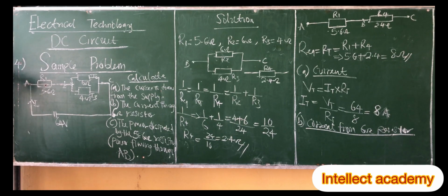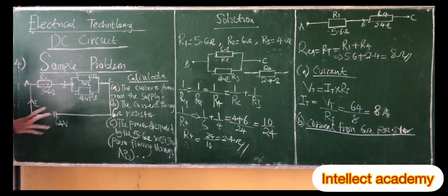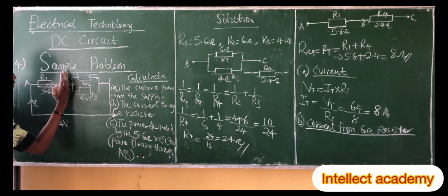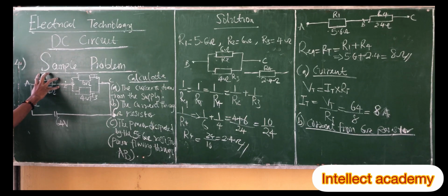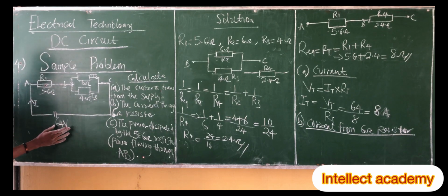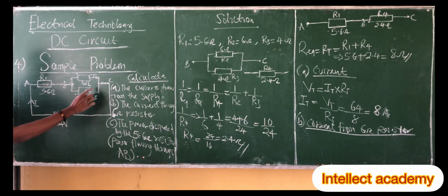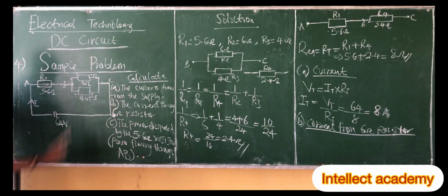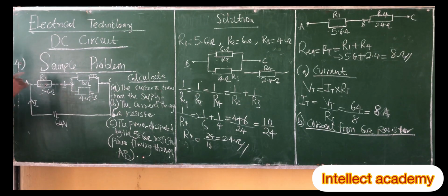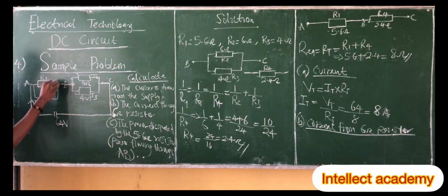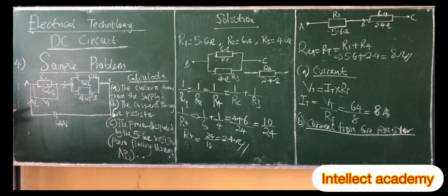It's very easy. Now what we'll do is we need to find the voltage, knowing that the voltage is equal at this point. We'll calculate the voltage for this, subtract it from 64. Then we're going to have the voltage flowing through this part. R1 has a voltage, so we're going to call this V1. We are going to calculate this voltage V1.